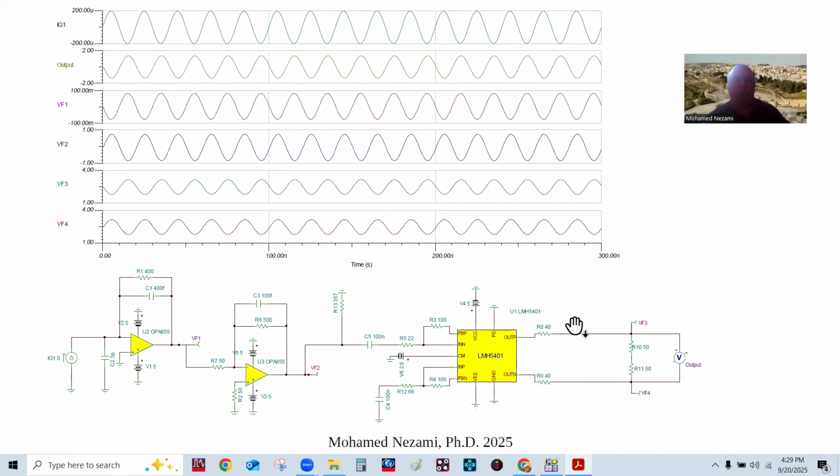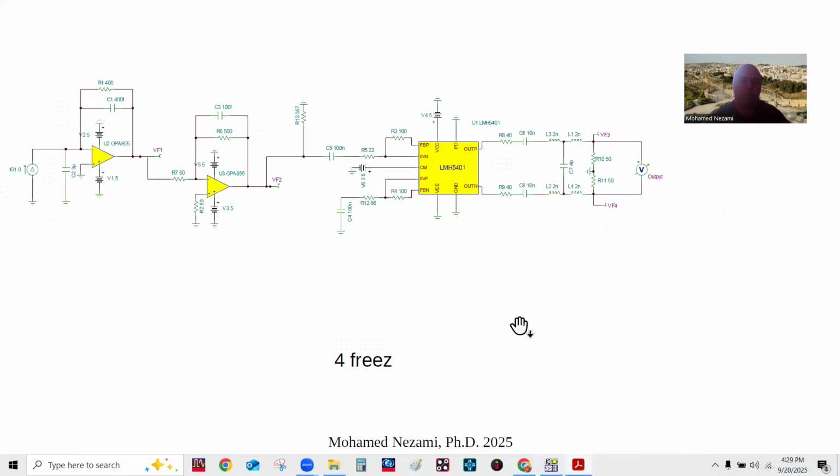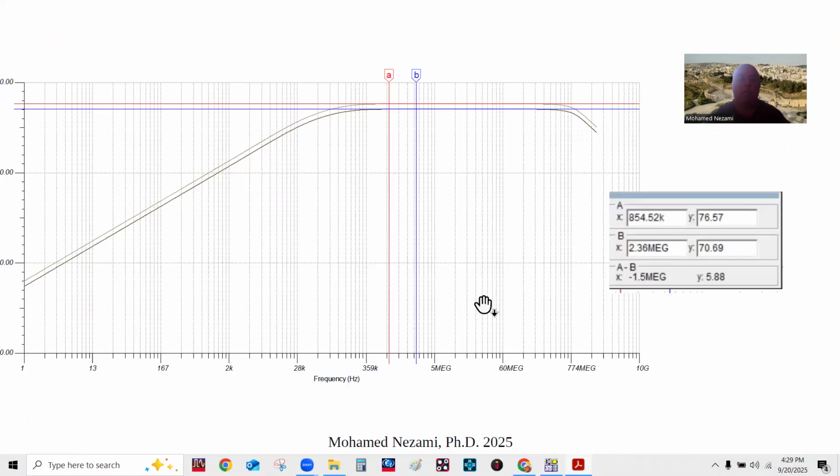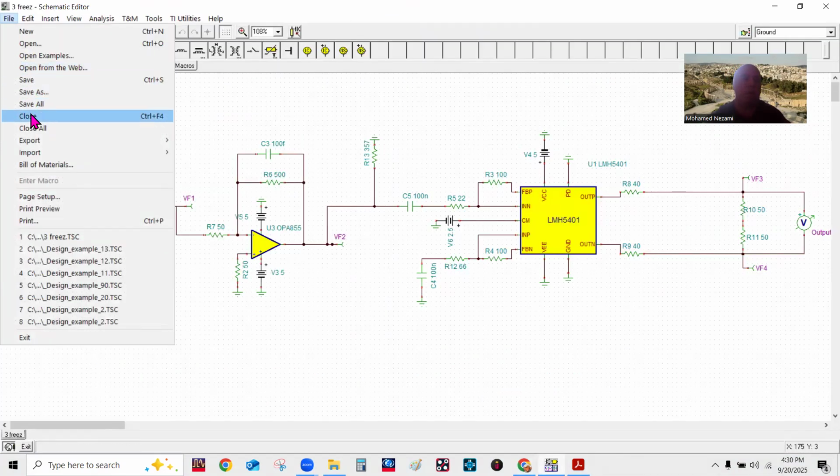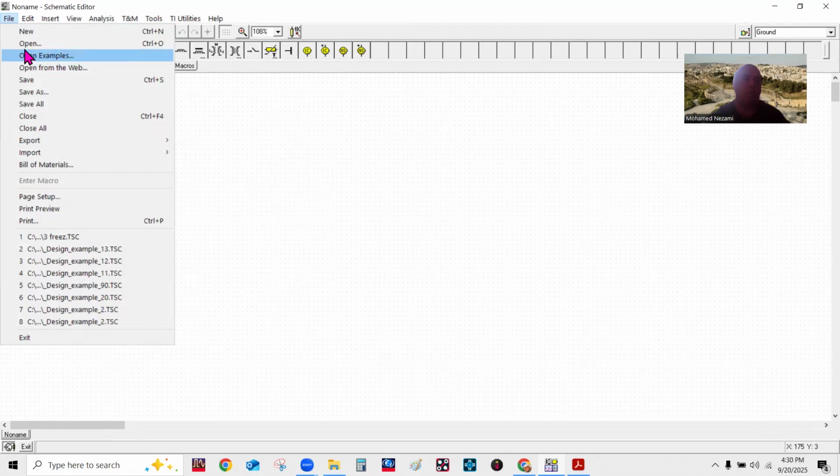So this is nice. This is ready. So this task is achieved. Now you can make this into bandpass if you want. Just add a little LC section in here, and that's what I did in here. So you end up with something like this. And let's go get that and look at it before we close the session.